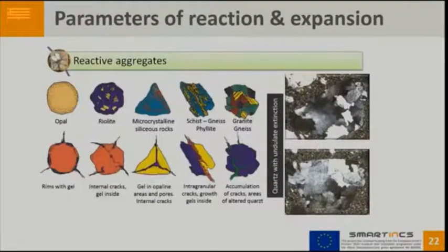Well, here we can see different ways of crack formation in aggregates, depending on the morphology, or much more depending on the composition. When we have a very homogeneous aggregate, the reaction products go from the surface to the interior of the particles.